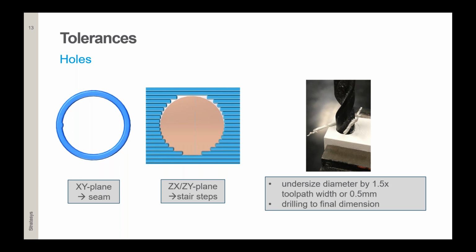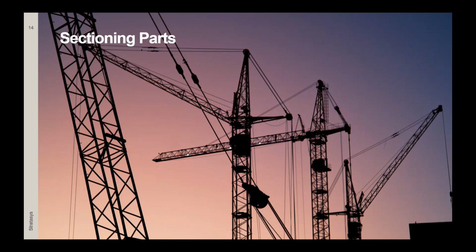Okay, so basically also when we print vertically, your advice is to use the diamond shape instead of a smaller diameter hole when drilling after, right? Exactly, yes. So you will have better guidance with the diamond shape, and you can drill it through as easily. Perfect, thank you. You're welcome.